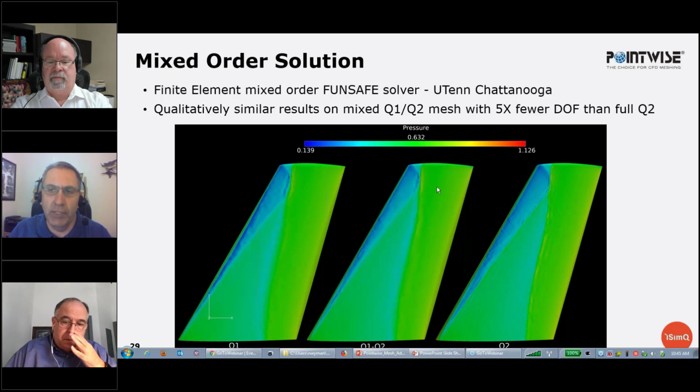So I think we all have comments about this, but I'll start. I'll say that definitely the mesh type is something that you need to be aware of. Your particular solver is going to perform better on a given type of mesh. I mean, we would all love to be running structured multi-block, perfectly flow aligned hexes. That would be the ideal scenario. But we do have schemes that are hex dominant and so forth. And which one's going to be better is going to be solver dependent.